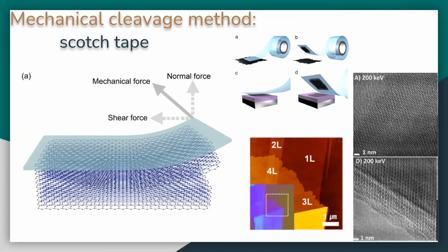Once placed on the substrate, the mechanical behaviors will strongly depend on the number of layers being extracted. So in the range of less than 5 layers, bending behavior from spontaneous rippling occurs. Homogeneous curving occurs around 10 layers of thickness, and kinking begins to happen at 20 or more layers.